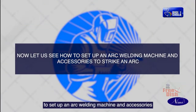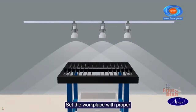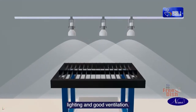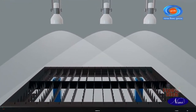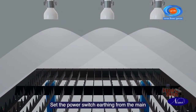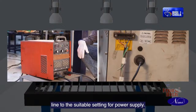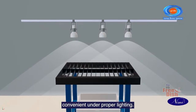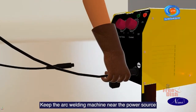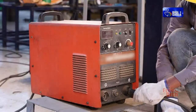Now let us see how to set up an arc welding machine and accessories to strike an arc. Set the workplace with proper lighting and good ventilation. Set the power switch earthing from the main line to the suitable setting for power supply. Keep the welding table convenient under proper lighting. Keep the arc welding machine near the power source and connect the power cable to the main switch.